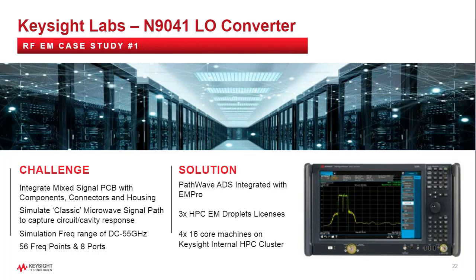The PCB is a 16-layer complex mixed-signal board integrated with some Keysight packaged devices, with a clamshell housing, gasketing material, and connectors. So it's a very classic microwave-type problem to solve. We're looking for cavity resonances, we're looking for circuit responses. It's very wideband, so we're running this from DC to 55 gigahertz over 56 frequency points.